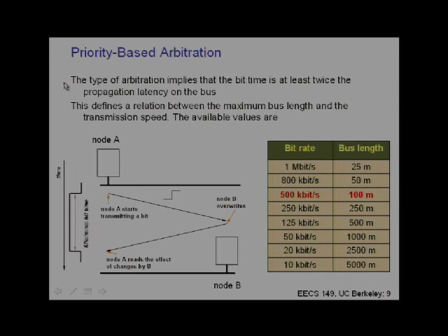There probably is, this is something I don't know the details of, some additional circuitry. It's not just the single node that's trying to pull it to a 0, but if that node tries to pull the bus to a 0, there probably is additional circuitry that will try to maintain a 0 level even when you have multiple nodes on the bus. But clearly you have a bound, due to those constraints on the number of nodes you can add, right? So even in theory, if you could have an arbitrary number of nodes on the bus, in practice you can't.